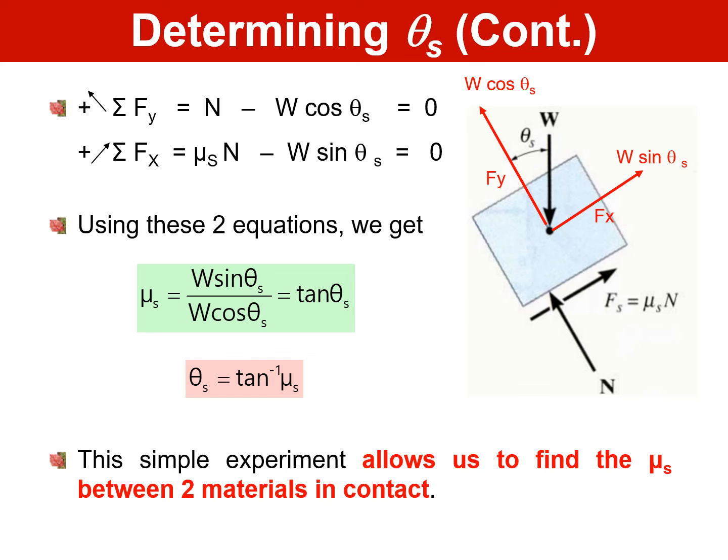From there you have your normal force and also your friction force, in which for this case the block is about to move. When it's about to move, it will be moving downwards, to the left. When the motion of the block is to the left, the friction force will be to the right, opposite to the direction of motion.